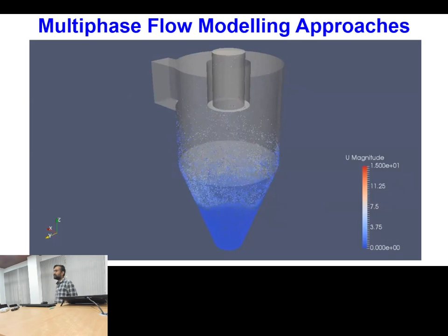So discrete element methods are popularly used by, say, the civil engineering community or solid mechanics people to study the effect of particle orientation and particle-particle interactions, for non-spherical particles. For our understanding of fluid dynamics, we are considering slurry transport and gas-solid flows. Here we are assuming that particles are of spherical shape when we use the Euler Lagrange approach. Is this point clear? So this is some introductory idea about numerical simulations and majorly what the common approaches are for solving multi-phase flow problems.